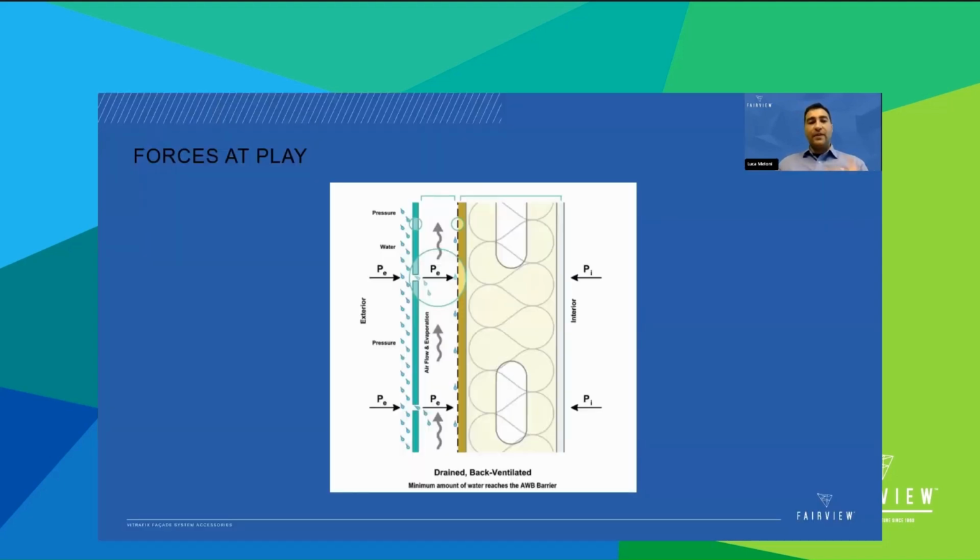There are different forces at play that affect our building enclosure. So far as the building enclosure is concerned, water is insidious. It can undermine the structural integrity, the bones of our buildings, and deteriorate the exterior. The additional expansive pressures of the freeze-thaw cycles and embedded moisture can literally crumble building facades. Entrapped moisture can also foster mold and rot that can sicken building occupants.